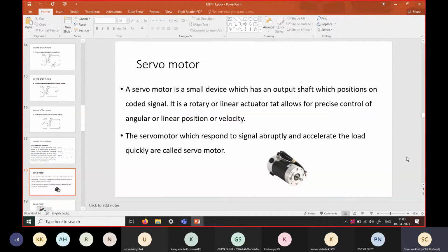The basic principle is that the voltage is always applied, and we send a signal to it to hold a particular position or to continue rotation at a particular speed. The commands are sent in a periodic manner to communicate the desired position and speed.